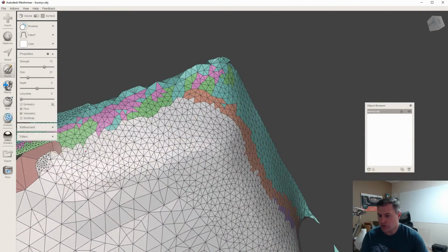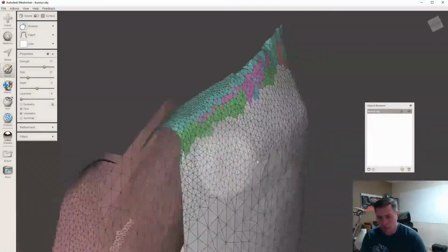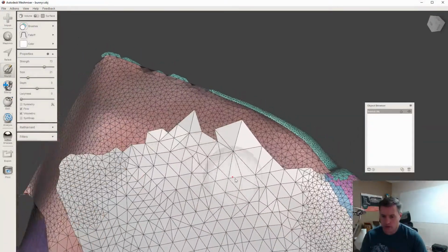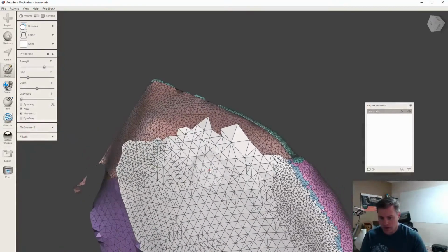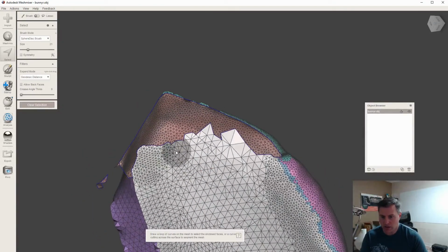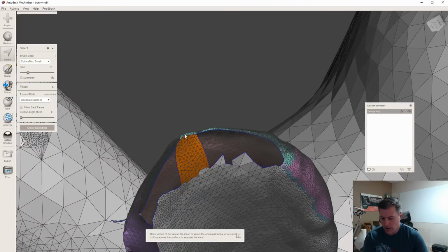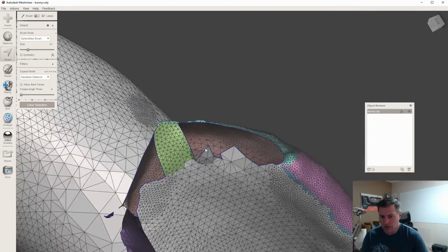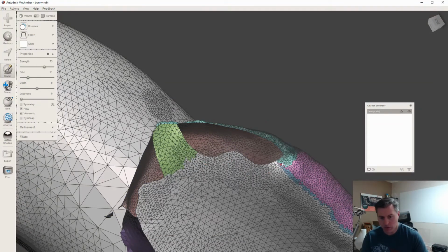Right, and that was just the result of the drag command, and it created some horrible geometry, but the robust smooth tool fixed it. So the way that I would fix the top ear of this bunny is just select a little part here, select a little part here, and bridge that. And I could certainly just double click on this hole or fill it, or I can go back to the robust smooth because it's just something I like about it. Something feels real good about